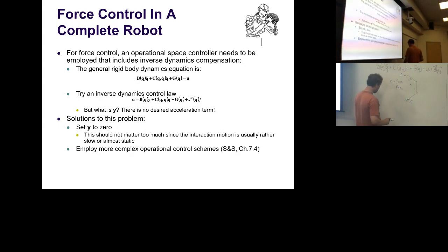So this would be U1, U2, etc. Now, if you remember this, this is how we define the geometric Jacobian. The geometric Jacobian is just modeling exactly these kinds of relationships. That's why the Jacobian transpose times force, just repeating that, tells me what torques to generate to hold out against that force. It's just statically holding out. So the moment you have interaction, you always get the rigid body dynamics equations which look like that.